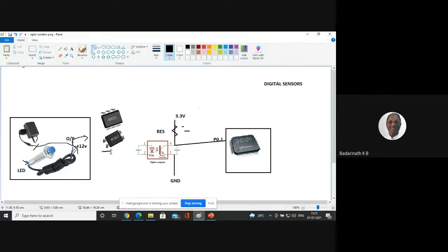I will bring one more resistor and connect it here. Now connect this point to here. Now I've done it. This already has a ground. The 12 volts and the ground you connected to this adapter, take the same ground and connect that ground to this point here. Now my connection is done.